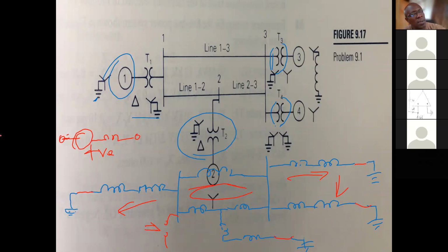So you had a fault on a little pole somewhere in St. Catherine, in a little swampy area. It leaned and created a single line to ground fault. It wasn't cleared by the breaker because of lack of maintenance, and it escalated into a major bus fault and collapsed the system, right? But in terms of analyzing faults occurring simultaneously, I would say it is not something that we need to consider, based on how the power system itself operates. Okay, sir. But if you want to learn more, we can talk in January. All right, sir.